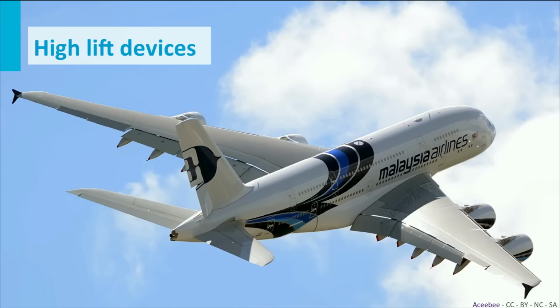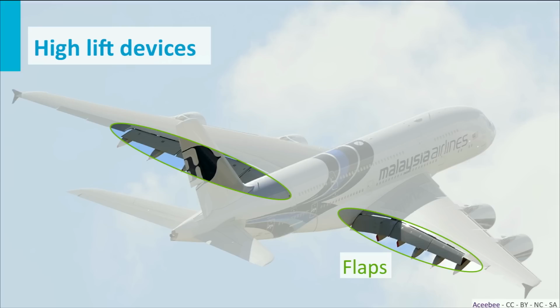In this picture, you see an Airbus A380 with high lift devices. First, I show you the flaps, which are used during landing and takeoff. Second, we can see the slats or leading edge devices, which are mainly used during takeoff. Both devices increase the wing surface area and to some extent they increase the camber of the wing profile and thereby increase the lift coefficient.